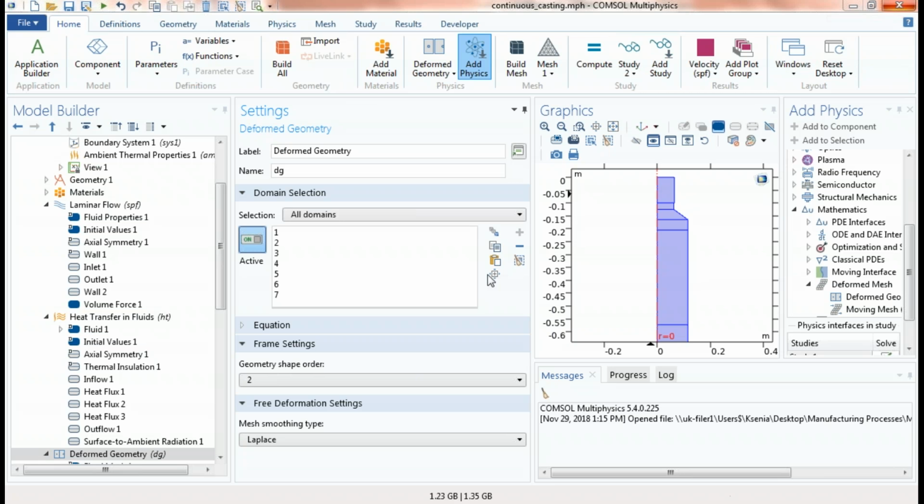So I guess certainly the process could be modeled as a mechanical or thermomechanical problem. You would need to set this up as a contact problem where you're modeling friction between the two parts, and you would need to convert the frictional losses into a heat source.